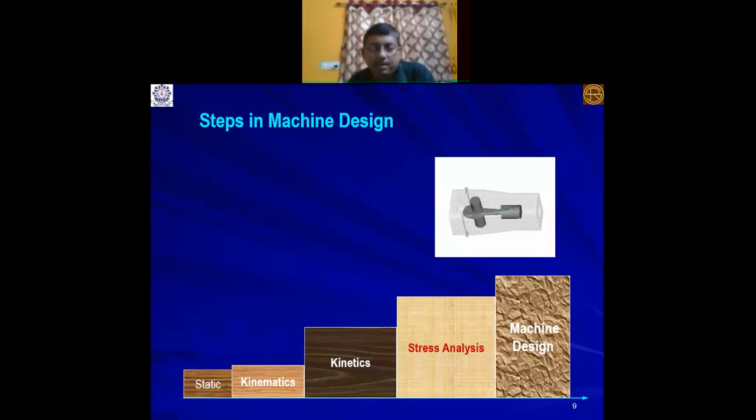Most of the time in mechanical engineering a static part is there. If it is a static part, then go directly to ANSYS. But if it is a moving part, to do the stress analysis of the moving part you have to solve the kinetics, meaning kinematics and kinetics. In CATIA, in SolidWorks, everywhere there is a motion solver. In CATIA it is called DMU Kinematics, and in SolidWorks, the motion solver.